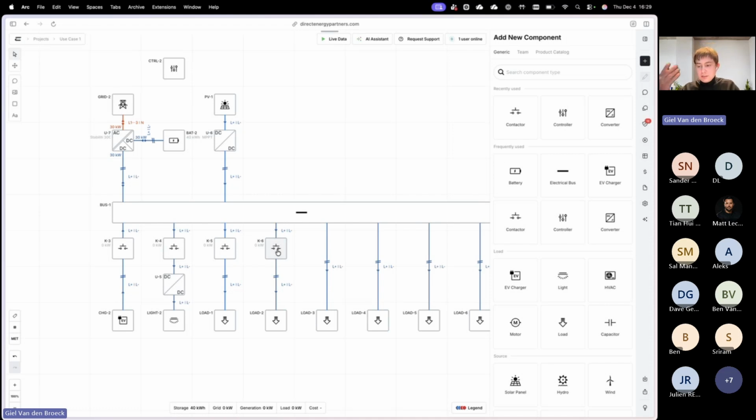We even have use cases where we took it to the next level, where we implemented droop control curves. In islanding mode, we wanted to run the system disconnected from the grid, without a battery and from solar only, so only solar supplying certain of the loads. Then your load needs to match exactly how much solar you have available at that point. If it's 10 kilowatts of solar, then you can charge your EV at 10 kilowatts. If it's 15 kilowatts, you can charge at 15 kilowatts. How did we accomplish that? By implementing a voltage droop control on our loads to support this mode of operation. We reduce their power output if the voltage on the DC bus decreases, and that way we always converge towards the balance between supply and demand at that time.